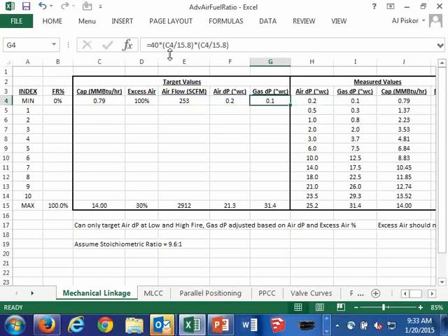So again, with the mechanical link system, I want to set my air pressures first. So I'm taking my mechanical linkage, and this is while the burner is off. So I have no gas flow, but I have the combustion air blower on and all the other system fans on. I can then go through and measure my air differential pressure, and set the linkage on my mechanical link micro ratio valve so that I get my air pressure at high fire and low fire.